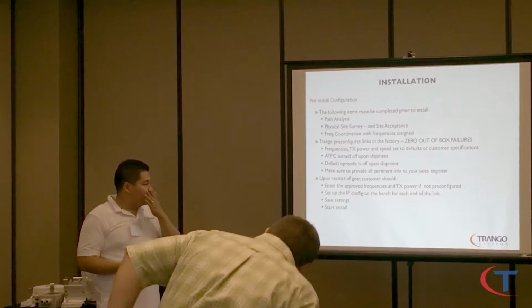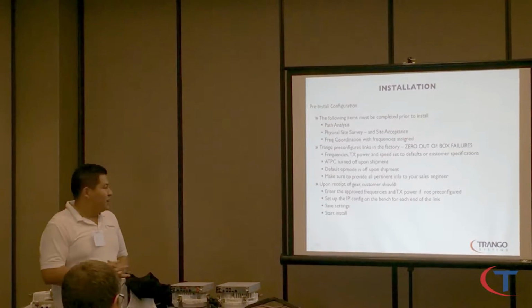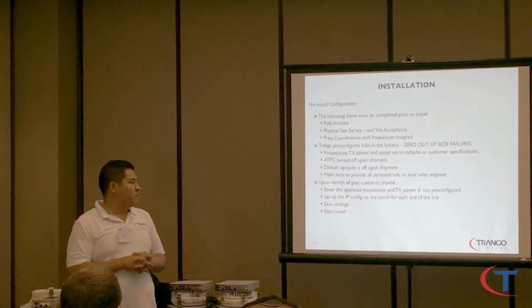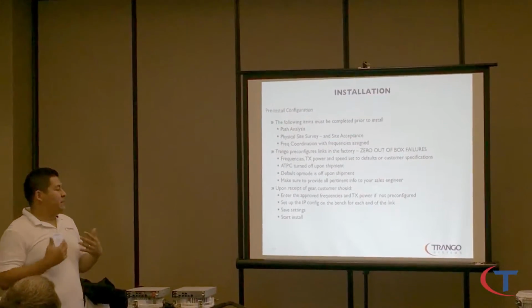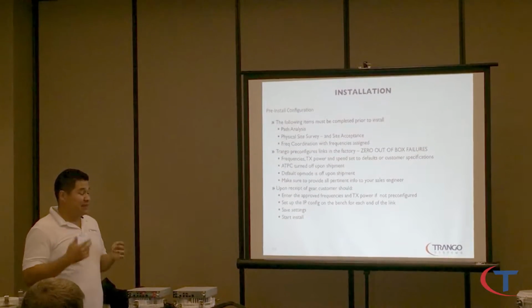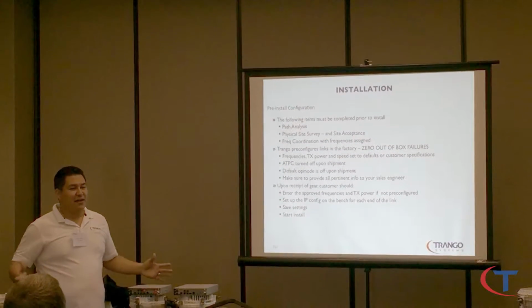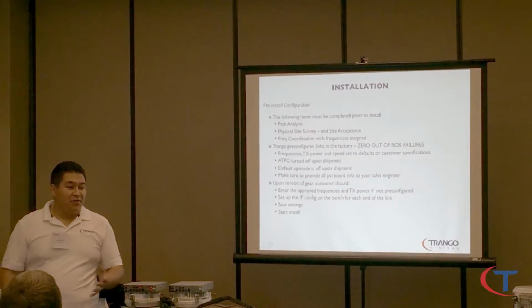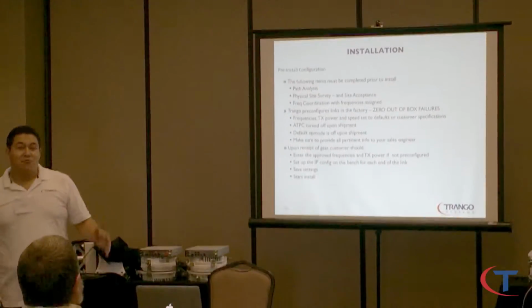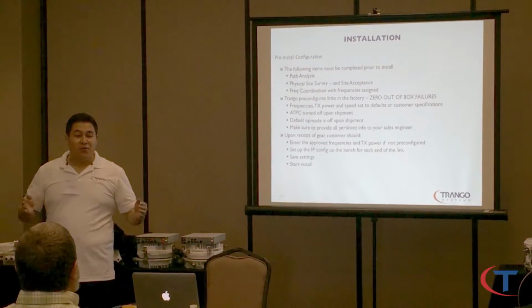Upon receiving the gear, what should the customer do? Enter the approved frequencies and TX power if not pre-configured, set up the IP config on the bench for each of the links, save settings, and start installation. Again, the number one thing of this training, if you remember my name, not that you hate me at the end of this training: remember, put it on the bench before you deploy it.